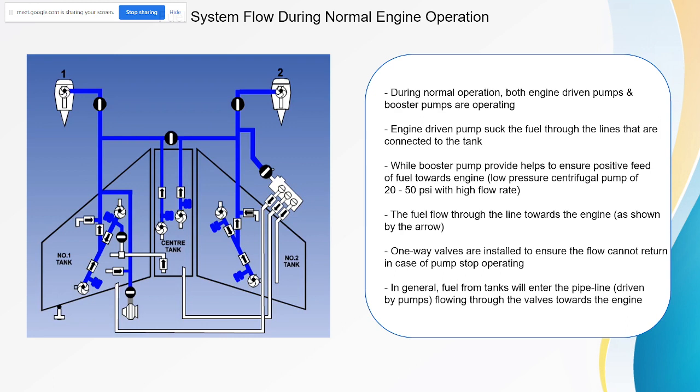You can see the refilling valve there. There's the refilling panel. There's a switch, and there's a check valve to flow one way. So depending on which tank you open, the fuel will go to that tank. And also it is to monitor if your tank is full already, then you can switch off.